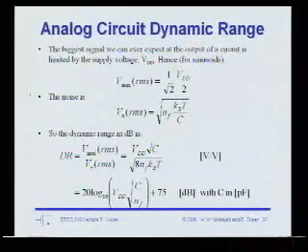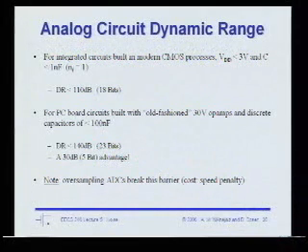All right. So here's an example which kind of brings everything home. Let's say you have a modern CMOS process, actually an old-fashioned CMOS process by today's standards, but let's say you're using a thick oxide device and you have 3 volts of VDD. And on chip, what's the biggest capacitor you can integrate? Well, 1 nanofarad is pretty big. If it's a linear capacitor, that's going to take a lot of chip area, but just for argument's sake, let's say you've managed to integrate a 1 nanofarad capacitor.